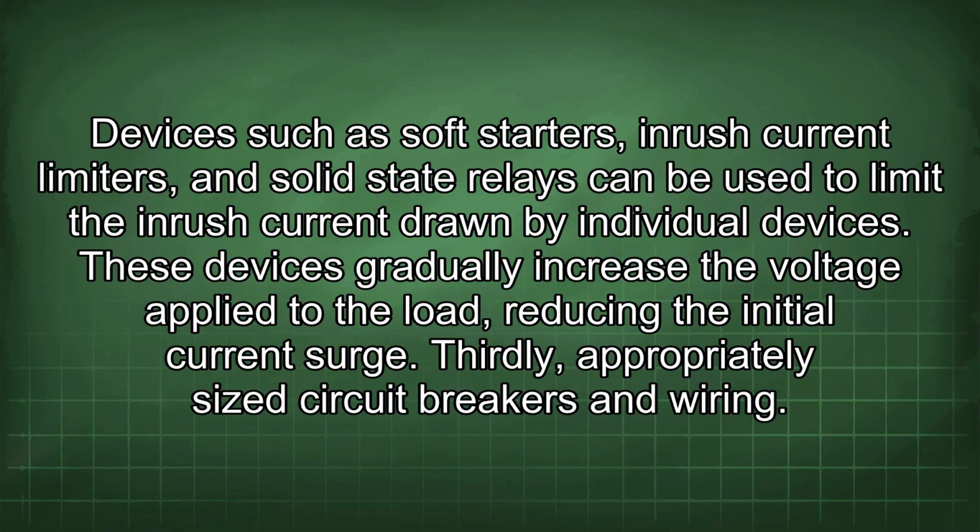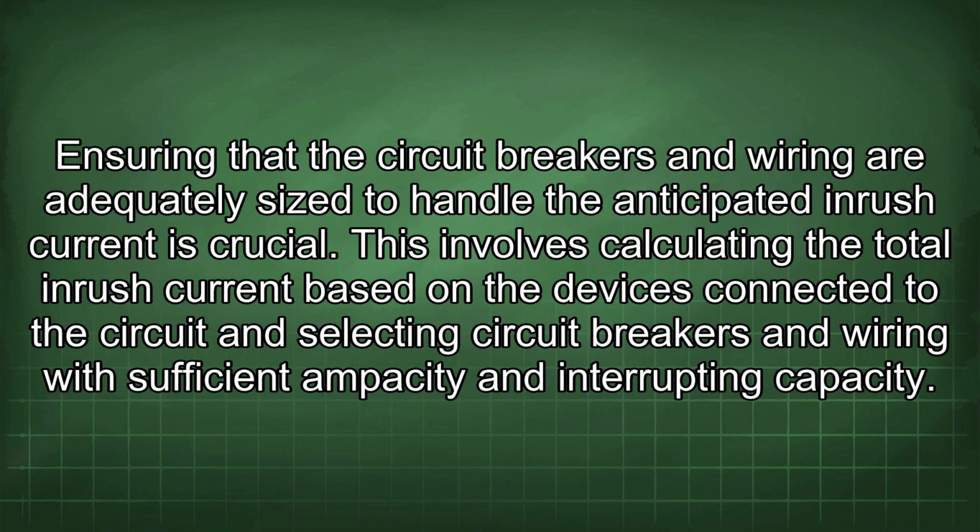Thirdly, appropriately sized circuit breakers and wiring. Ensuring that the circuit breakers and wiring are adequately sized to handle the anticipated inrush current is crucial. This involves calculating the total inrush current based on the devices connected to the circuit and selecting circuit breakers and wiring with sufficient ampacity and interrupting capacity.